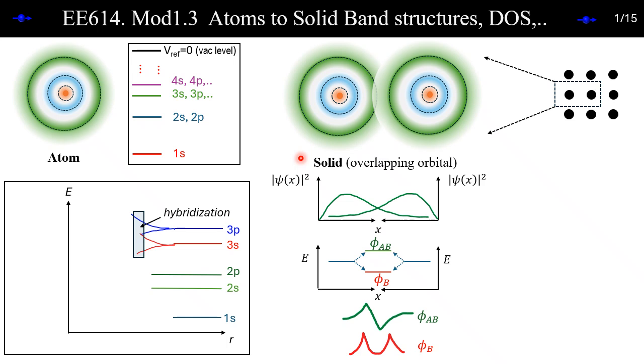This is kind of a thought experiment, a very intuitive understanding, that initially energy levels will split and eventually they will merge and hybridize, and the atomic spacing of silicon is such that we have the conduction and valence bands. And we have seen that the core electrons do not split much because their orbital overlap does not interfere significantly. So this phenomenon takes place primarily with the outermost shell electrons, right?